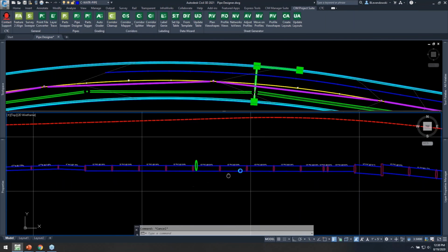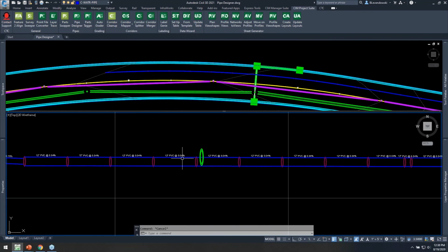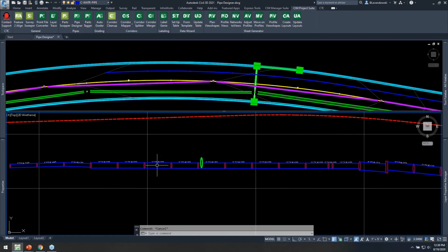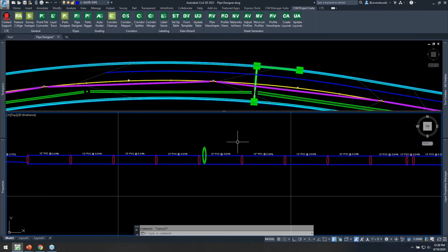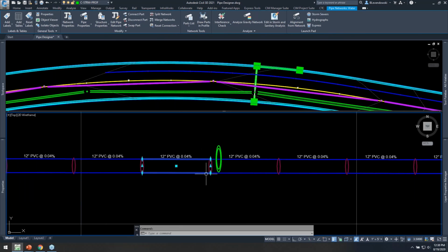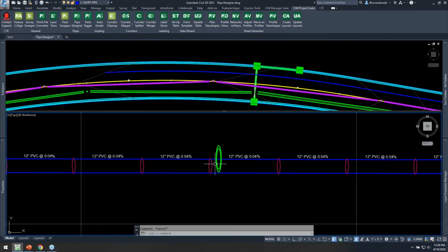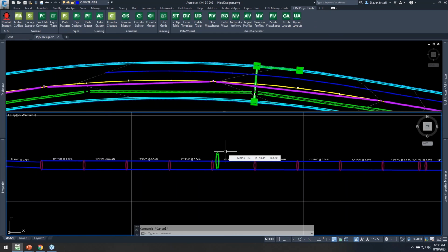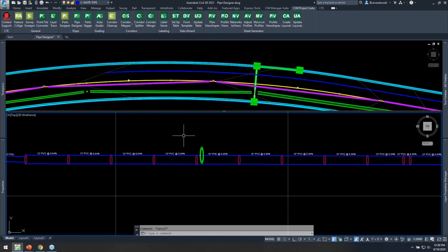Okay. And you can see it's violating, right? We've got that storm, the water main is in the way. We can't move the storm, so the water main needs to go around it. We can't go above it, we need to go below, so we maintain that minimum cover. And normally you'd be grabbing these pipes and manipulating them, but it gets really tricky to work with because, do you need to put in a 45-degree bend? Can you just angle the joints a little bit so long as you don't violate your deflection? It depends on how much you need to slope this stuff and what you're doing.